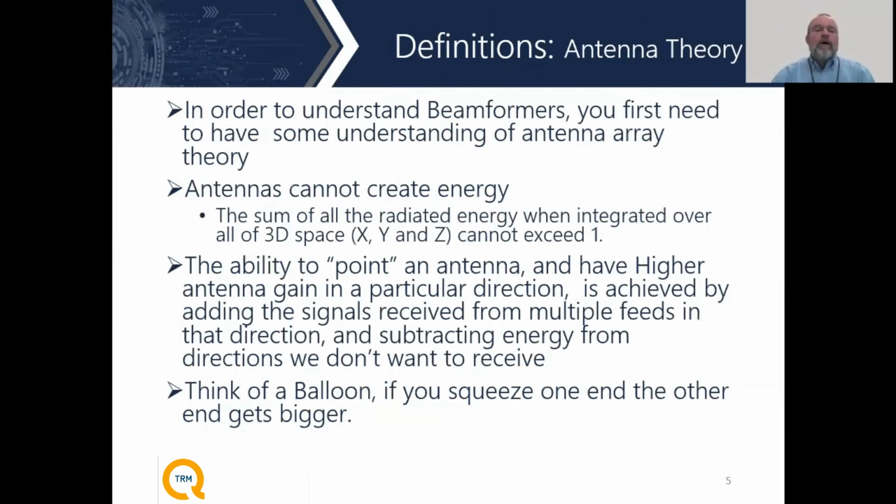Yes, absolutely. Like I mentioned at the opening, in order to have an understanding of beamformers, you have to understand a little bit how antennas work. Antennas, by their nature, take a signal that is on a transmission line and translate it into a wave that crosses space and time. The energy goes from the antenna and spreads out over space.